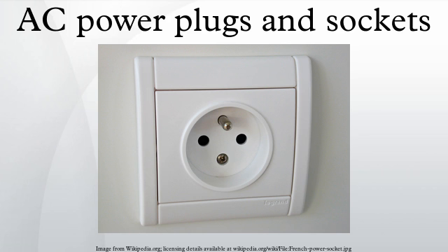Soviet adapter plugs. Some appliances sold in the Soviet Union had a flat unearthed plug with an additional pass-through socket on the top, allowing stacked arrangement of plugs. This design was very helpful, but somewhat unsafe, as the brass cylinders of the secondary socket were uncovered at the ends, recessed only for 3 mm and provided bad contact because they relied on the secondary plug's bisected expanding pins. The pins of the secondary plug could not be inserted into the cylinders completely, and were accessible through a 5 mm gap between the primary and secondary plugs.